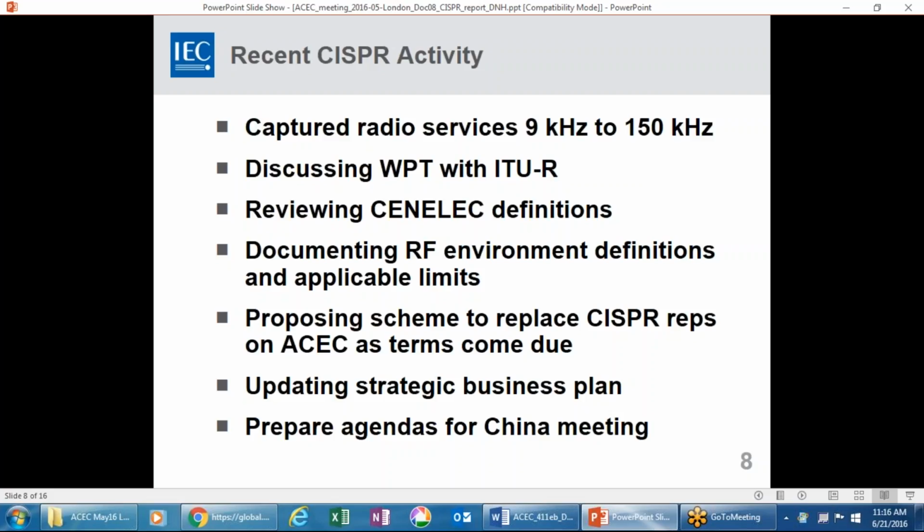But on the other hand, all the power inverters and the grid-connected power inverters, namely the brick you have serving your PC, for example, is putting out emissions in that frequency range. It's above just 50 or 60 hertz, all the harmonics. And they have to work compatibly, if I can use that word. So there's a lot of action on what should be the limits, and how do you measure these? Should it be a conductive measurement, or should it be a radiated measurement, like a radiated magnetic field measurement? And that argument is going on, and research on what's the best is going on.